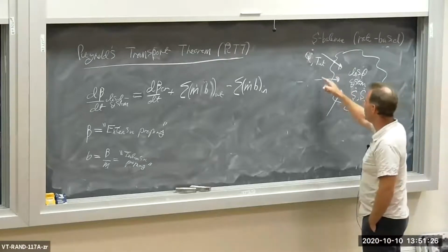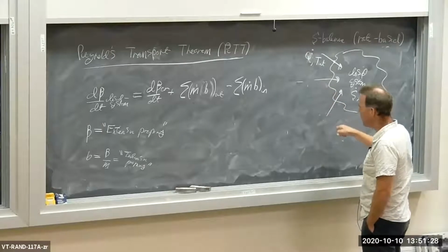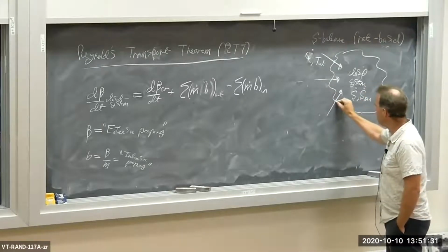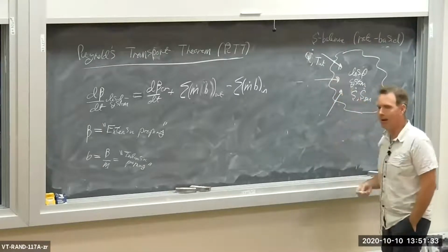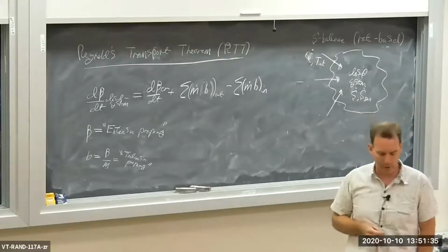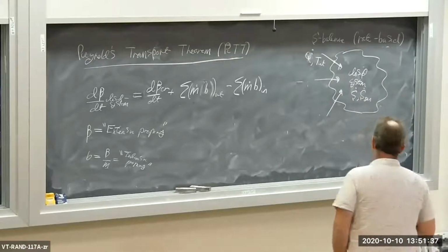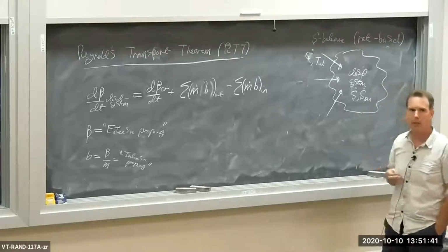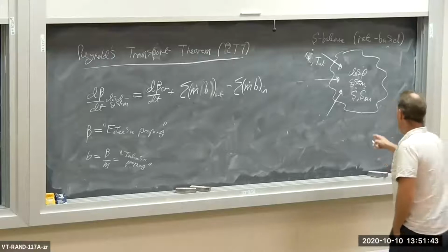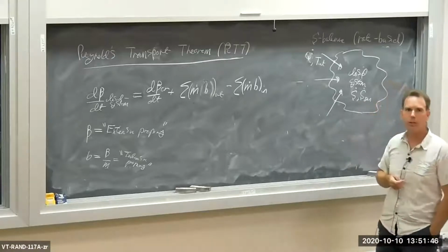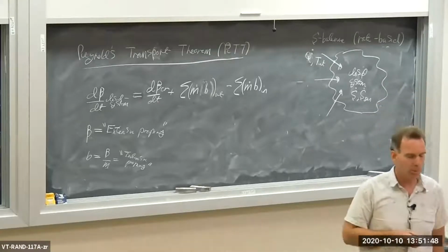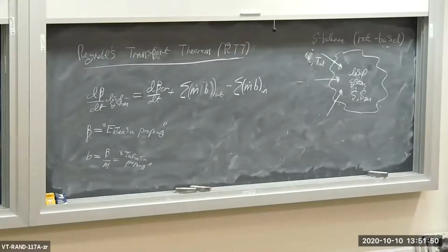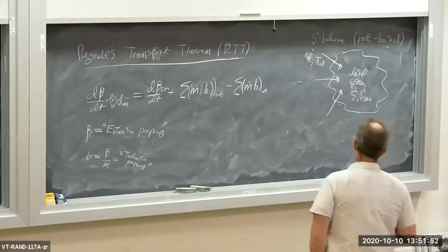And we have multiple heat transfers. There could be many heat transfers with many temperatures here at the system boundary where the heat crosses into the system. And that all results during some process in a rate of change in entropy within the system. And of course, there may be some entropy generation in the system due to the presence of some sort of irreversibilities.